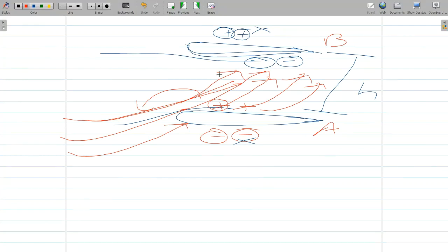So when these free streams essentially bend, initially your free stream was coming in, let's say, in a straight manner. Now you have some added on velocity in the upward direction over here. So your resultant velocity will basically be in this way. So that essentially would increase your angle of attack, or you would get what we call an upwash.